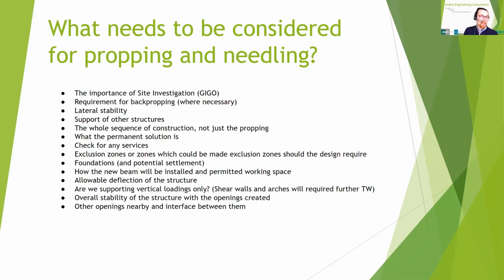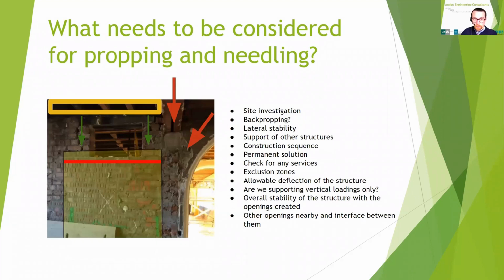And then finally, ask yourself, is the solution buildable? It's very important that the design from both the permanent works and the temporary works is buildable and suitably mitigates the risk using the ERIC principle of eliminate, reduce, inform and control. Openings in load-bearing structures can go seriously wrong if not carried out correctly, and the overall solution must be safe and the sequence of the construction must be practical.